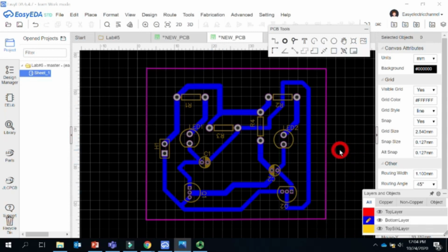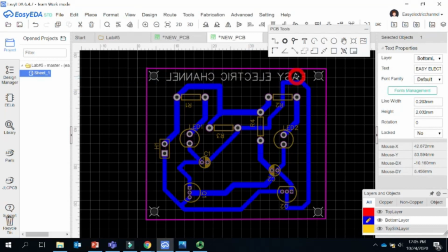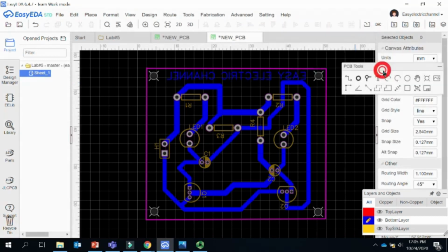The other things you could put are your name, and also usually each PCB board has some holes to attach it anywhere that you want. So here I put these holes. If you are interested in having some name on it, you put this here. If you click, you just type your own name, okay? I'm typing my YouTube channel here. Depending on the room that you have, it should be fine. If you need more room, you could expand from one side. So don't forget to save it.